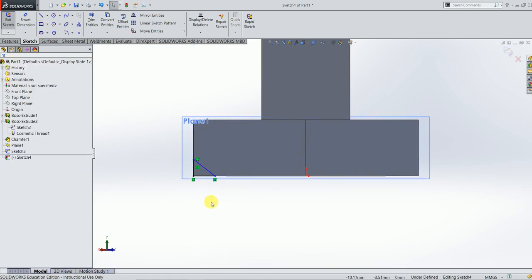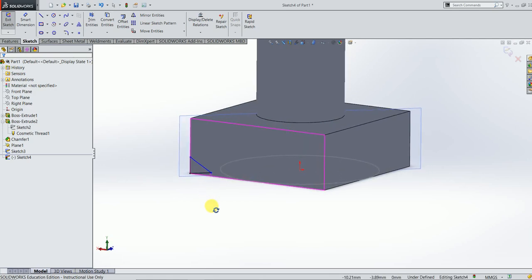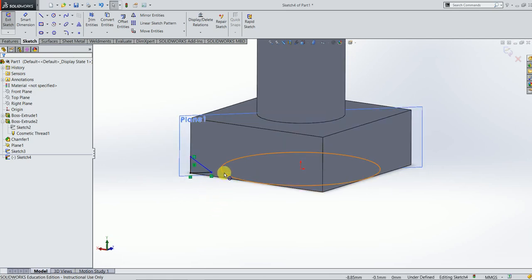So this triangle actually represents... So now you can see there is a circle appearing here, and this is the triangle that I have constructed on the plane which is passing through the opposite corners. Now for this triangle shape, the material should be cut around that created circle. Means like this. So for this triangle shape, the material should be removed around the created circle.